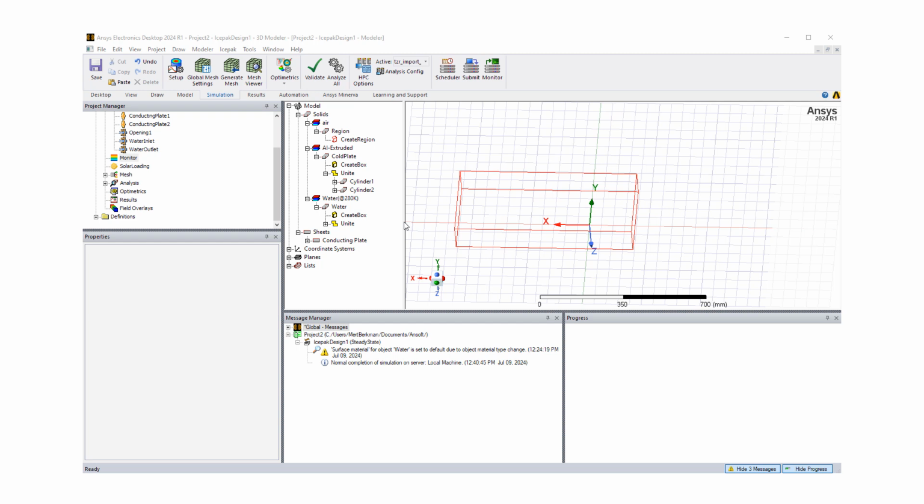Since we want to get a converged solution, what we want to do is monitor some key values at each iteration, so that we can check the convergence. What you want out of convergence is that the monitored values should stop changing with iterations. Because this is a thermal problem, we want to track temperatures. We also have some fluid flow, so we're going to add one monitor to maybe track the water mass flow rate. So how can we do this?